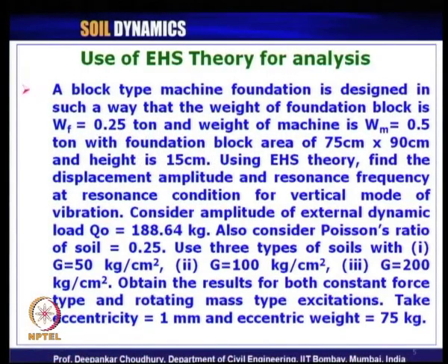We will now try to solve this problem, which is again a design check problem. The problem statement says, the same problem we are taking, the only difference is, instead of displacement amplitude at operating frequency, now we want to compute displacement amplitude at resonance condition and also what that resonance frequency is. These two pieces of information we want to compute using elastic half space theory. Okay.